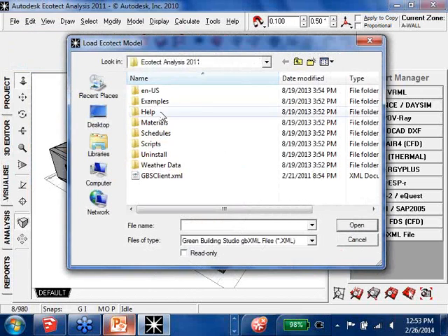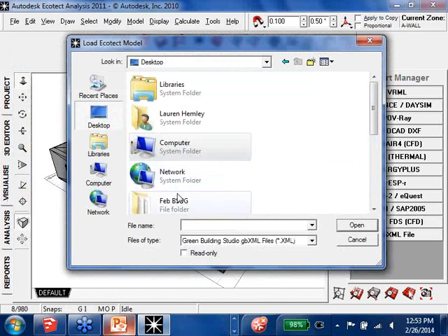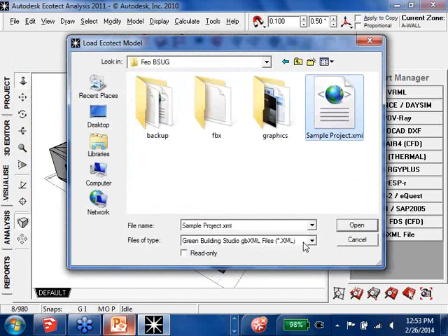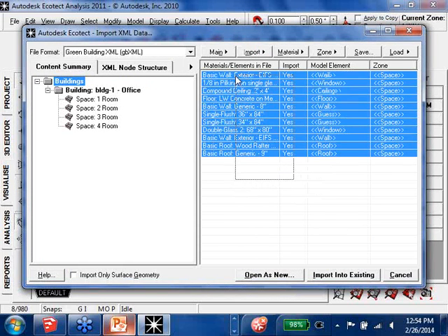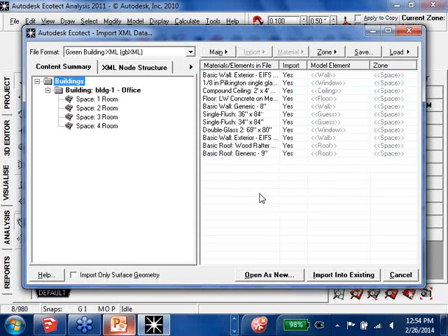I want to constantly talk about the translation from Revit to these other programs, and this is a way to show that these are the Revit materials, because we clicked on that Include Thermal Properties tab. If we didn't click that thermal properties checkbox, then it would use the conceptual constructions that are applied to the model in a template hierarchy, but they don't show up in the GBXML export process.